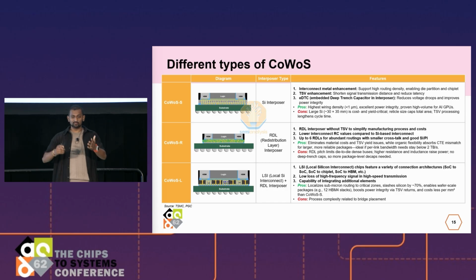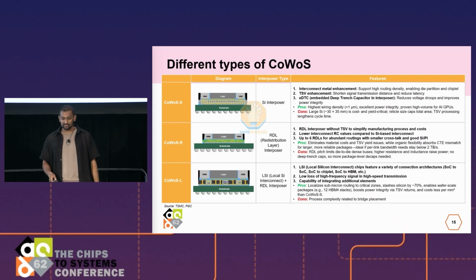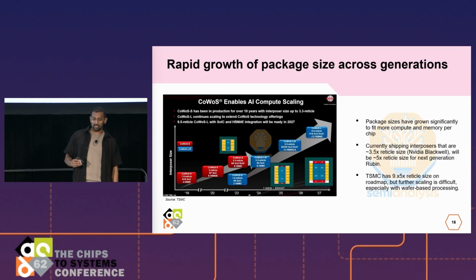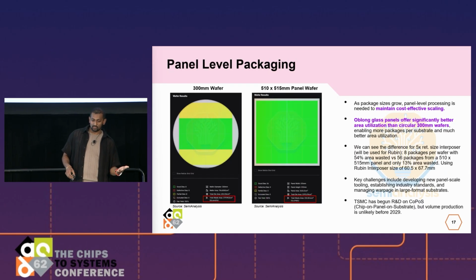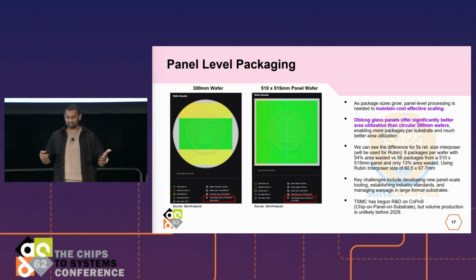There is some scaling there, right? Most standard chips have 130 micron bump pitch, but within the silicon interposers, we're getting down to 35 micron for next generation designs. So that's roughly 8x density increase. And these packages are getting much larger, but more importantly, some interesting things are happening with regards to the sizes